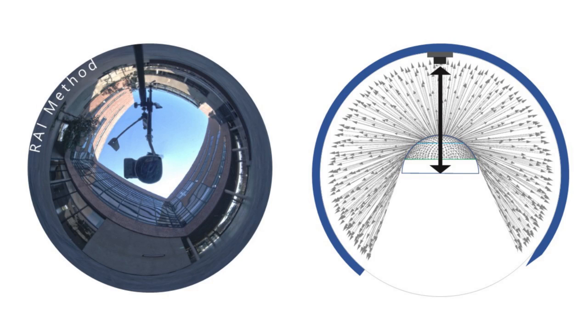The Radiant Ambient Imaging, RAY, method is used here to capture the most critical parameter, mean radiant temperature, MRT, and calculate the radiation flux from each surface, while other parameters are recorded by other sensors simultaneously, such as airflow, humidity, and air temperature. For the setup, a camera is placed on top of the silver hemisphere to capture the context.